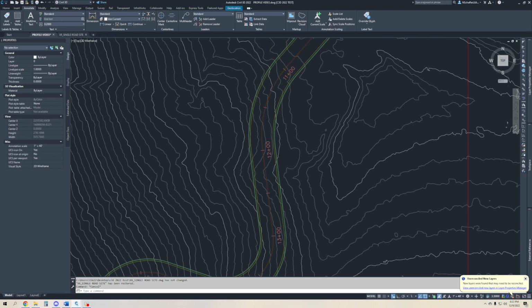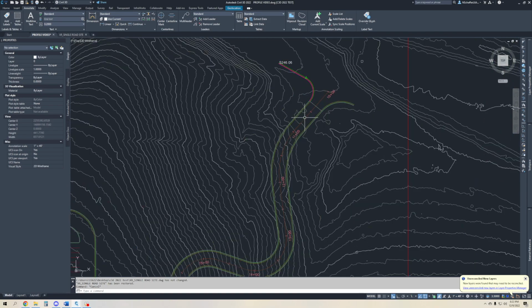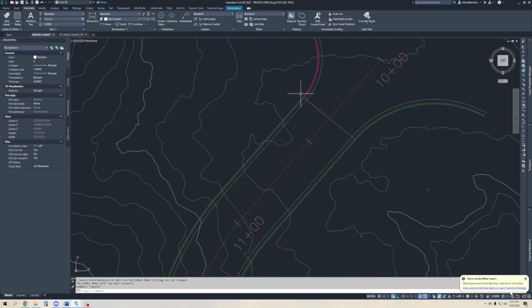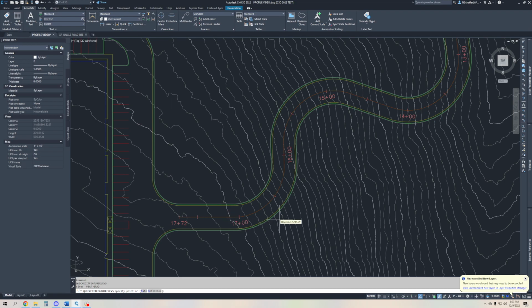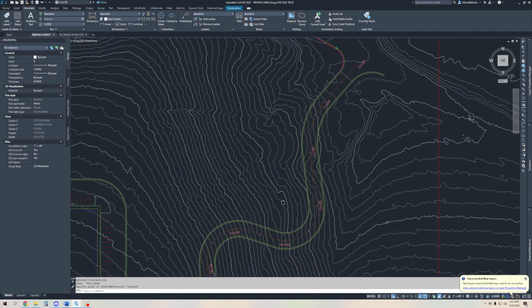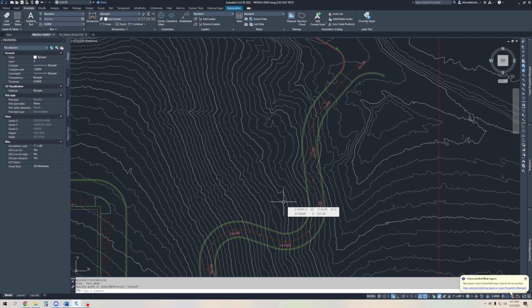And the nice thing, if let's say I didn't get as high as I wanted my elevation to be higher up, I can then just select this point again, change it to 2% up to this point. Let's say I change it to 2.5% from there to the top of my road. It's as quick as a couple button clicks to edit the elevations across this huge feature line that would otherwise take a very long time if I'm doing it through Elevation Editor or Quick Elevation Editor. So it's a very helpful tool, something I use all the time.